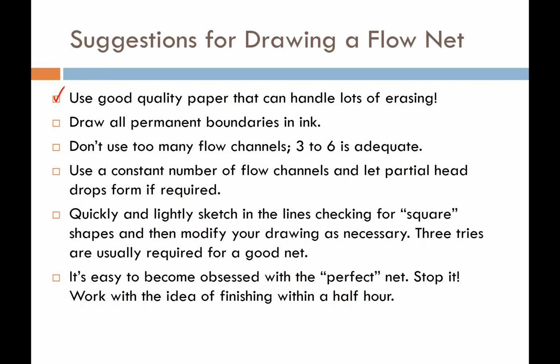I recommend when you draw the flow net on your paper for the first time, or actually draw just the problem, before you draw the flow net, draw all of your permanent boundaries, like the ground surface, maybe the impermeable layer beneath the soil. Draw all that in dark black ink. If you have a hydraulic structure like a dam, draw that in ink.